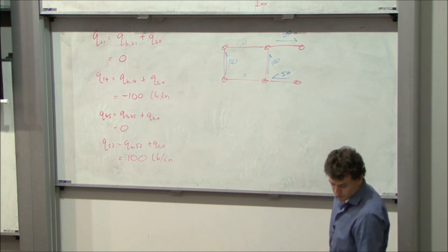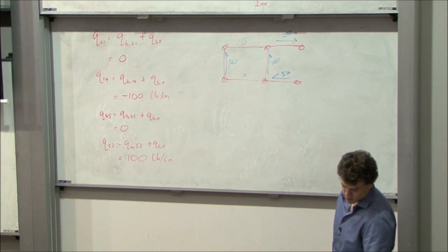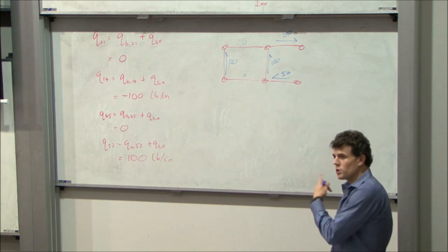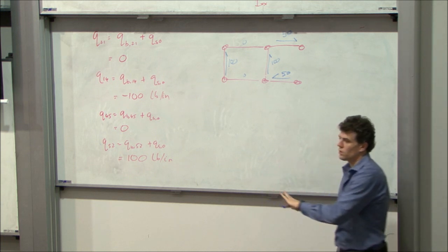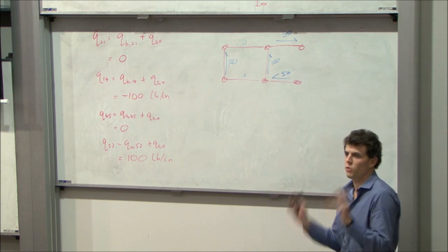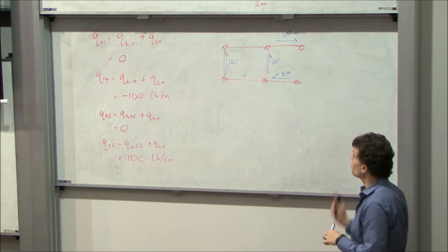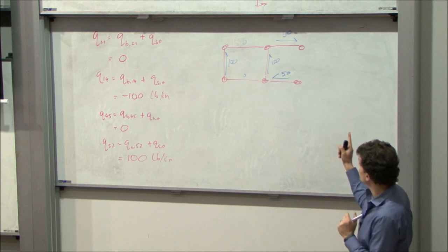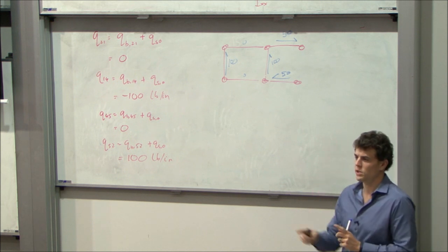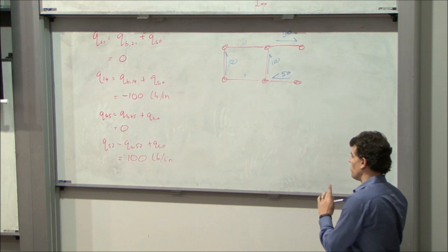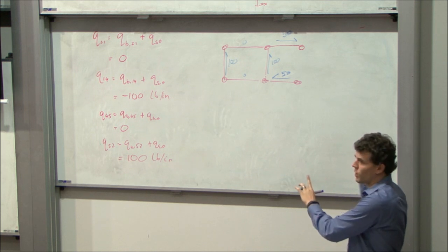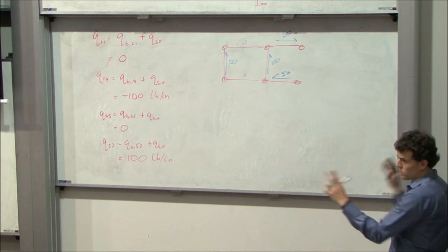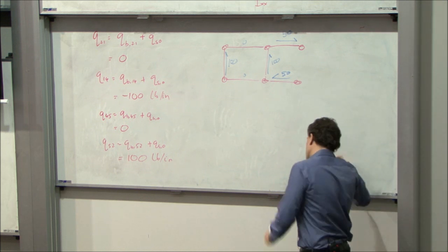So that example is written up in the notes, so you can follow that at any stage. Now at this stage, for this question, I didn't address how to calculate where the shear centre was. I just said we're applying it at the shear centre. In a general problem, if you've got a position for your shear force, you've got to work out the shear centre first, move your force from where it was to the shear centre, and apply an equivalent torque to get to the same force system.